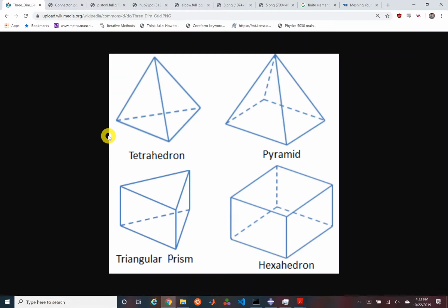But what you'll see, and we'll see in this, is that constructing hexahedral meshes is not a trivial problem. And so oftentimes folks will use tetrahedral meshes, as you can typically always construct a tetrahedral mesh of at least okay quality. But there are some challenges with tetrahedral meshes.